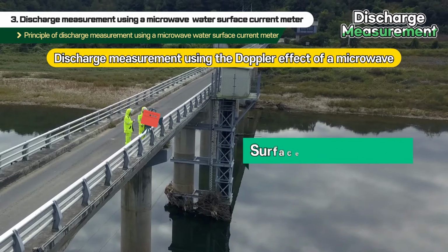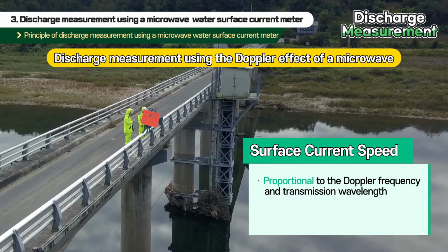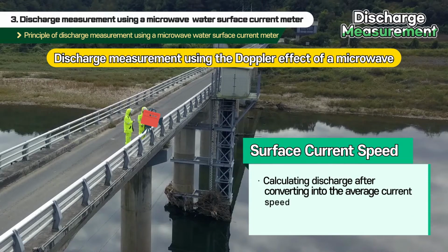At this time, the surface current speed is measured by using a characteristic that is proportional to the Doppler frequency and the transmission wavelength, and is inversely proportional to the communication antenna slope value. The surface current speed calculated in this way is converted into the average current speed using a developed calibration skill to calculate the discharge.